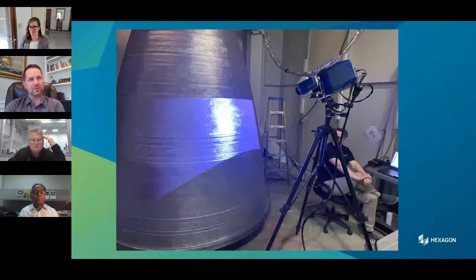Beyond that, when we start using some of the acceleration approaches to make the models go much, much faster, there can be some additional steps to start with a test article like the test cone that we showed earlier. When you have a part with a distortion value, you might need to perform some scaling, just because when you're applying that much material at one time, virtually, you can get some interesting effects.